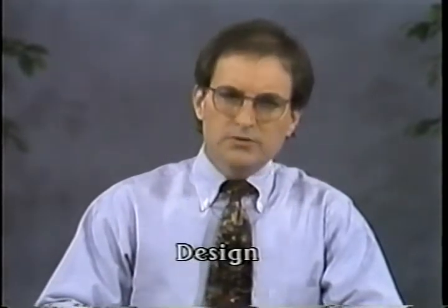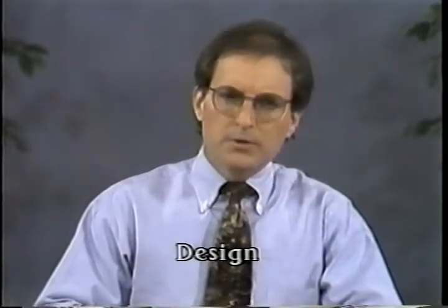The design phase of the project is undertaken with large-scale mapping generally produced by photogrammetric methods. Traditionally, designers have used paper maps and designs have been done on hard copies. But this method is being rapidly replaced by the use of 3-dimensional digital terrain models and computer-aided design and drafting systems. The first step in the design phase of a project is to determine an alignment.